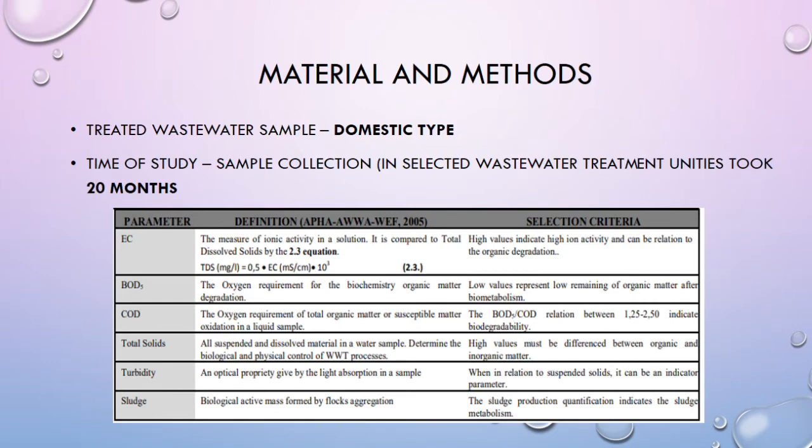Next, the definition of biological oxygen demand is the oxygen requirement for the biochemical organic matter degradation. For chemical oxygen demand, the definition is the oxygen requirement of total organic matter or susceptible matter oxidation in a liquid sample. Total solids definition is all suspended and dissolved material in a water sample. It also determines the biological and physical control of wastewater treatment processes.